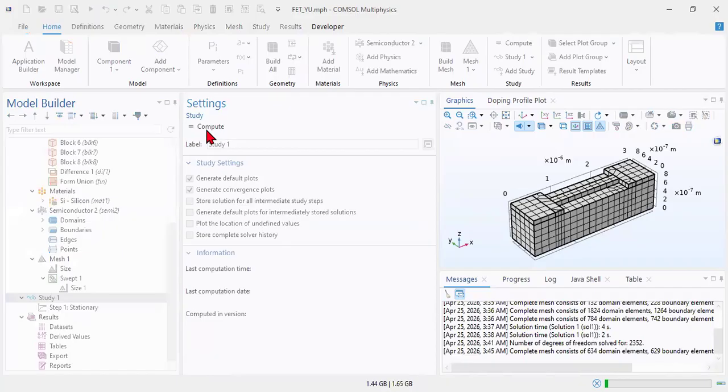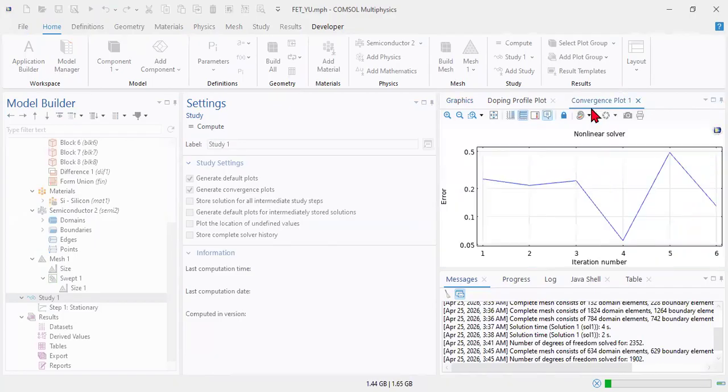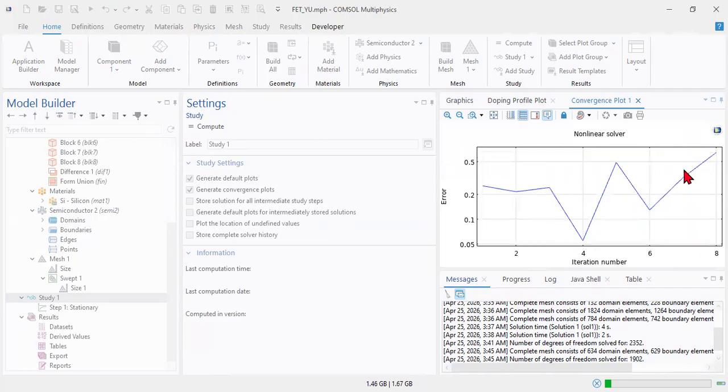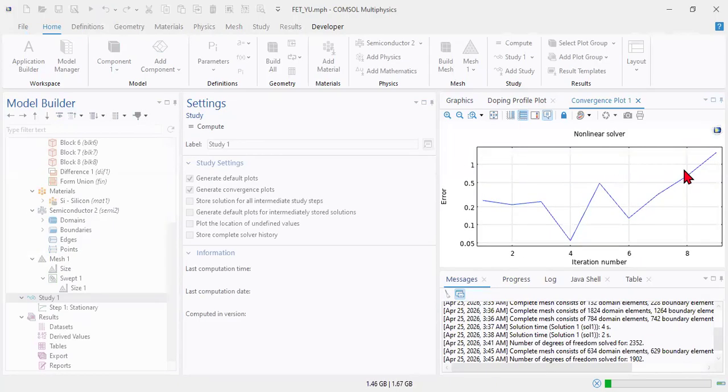Basically, if it doesn't show any specific problem, then in that case the maximum iteration limit is actually pointing to a problem in the mesh. So we need to take a precise mesh. Again, it's bumping, so I don't think it has fixed the problem.